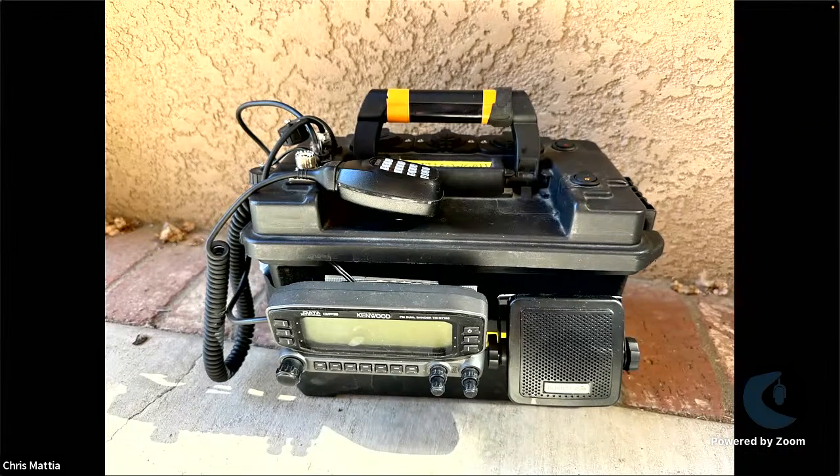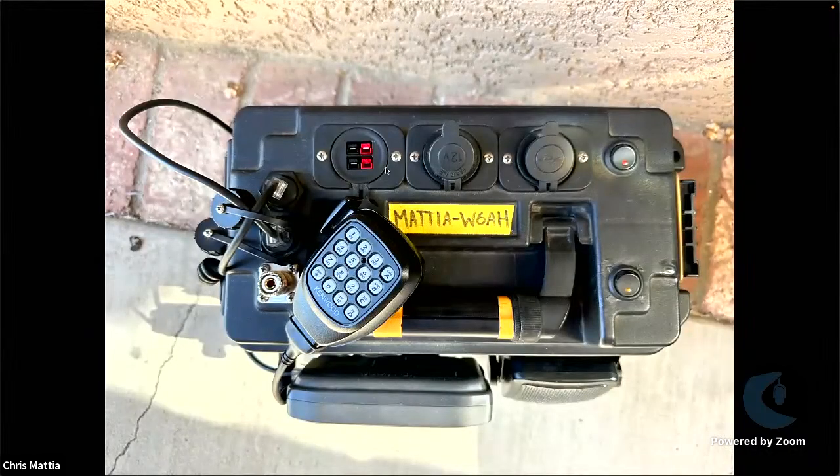This is kind of my portable go box. This is for my VHF UHF, and it's a little plastic ammo can that I've converted into a go box. I use Velcro on the outside for the radio head and the external speaker. On the top of it, I've put inserts for power poles, a 12-volt socket connection, and some USB ports. I've put in two circuits, one circuit on the top for all of the charging and external power, and then the second circuit, which actually drives the radio. On the top, I've moved the ports for my radio up to the outside, including an antenna port.